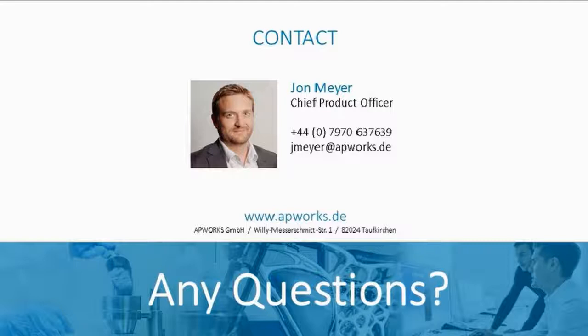It depends on a couple of things. One is the material itself, and the other is the process parameters that are applied, so what the layer thickness of the process is. Generally speaking, they're somehow coupled. So alloys which require a lot of energy to melt and have low thermal conductivity, so think of things like titanium alloys, tend to have a better surface finish, things like steels as well and Inconels,